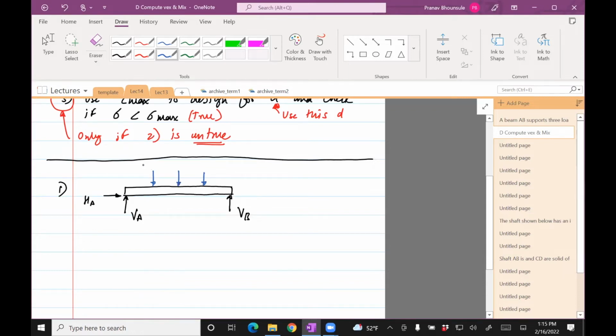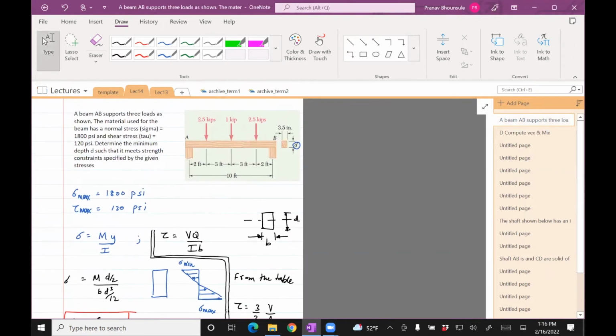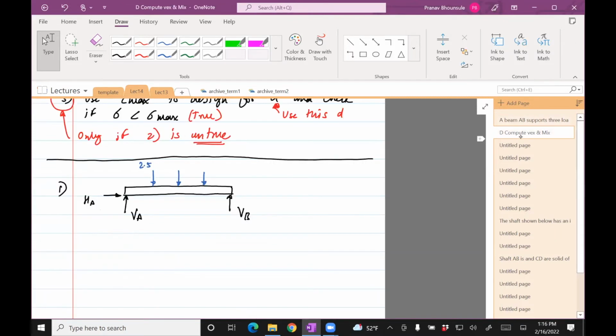Well, this is a system which looks like it's built out of wood, right? And then the thing is, you want to make assumptions. And when you make an assumption like the one I assumed, you want to check if the assumption is true in the real system. Just to make it tractable, in this case, I assumed it to be pin and roller. But yeah, you would want to possibly do it with other kinds of supports and see if that's a better assumption for your system.